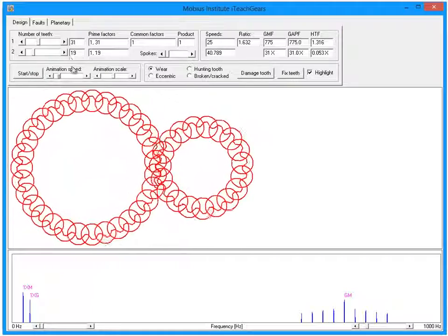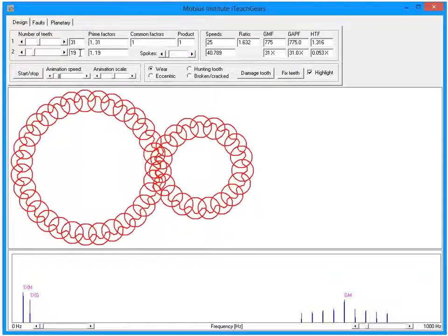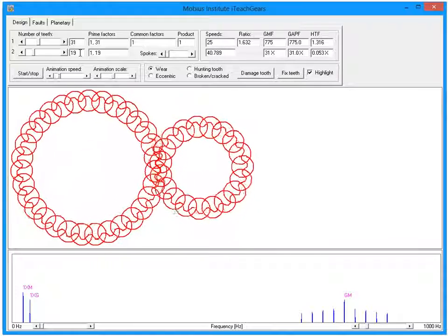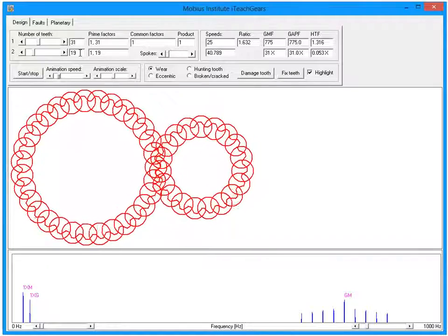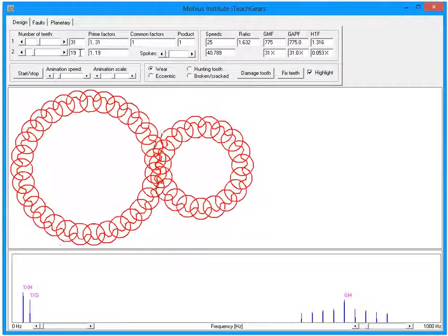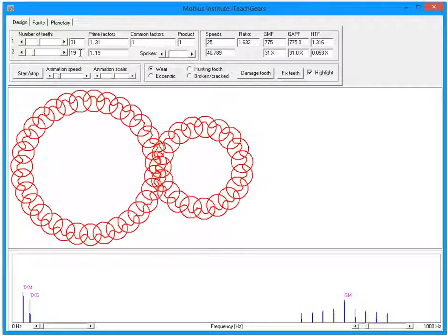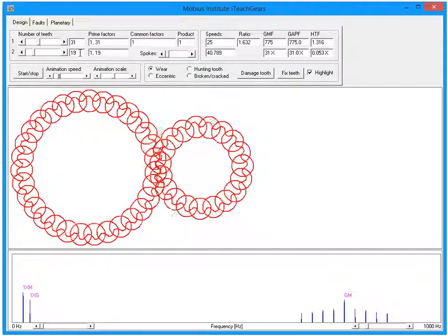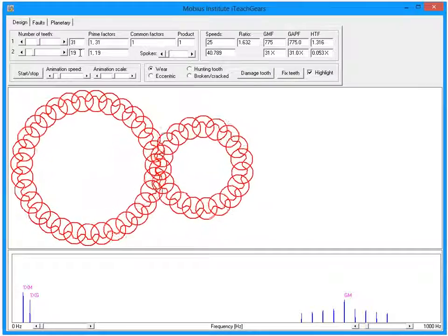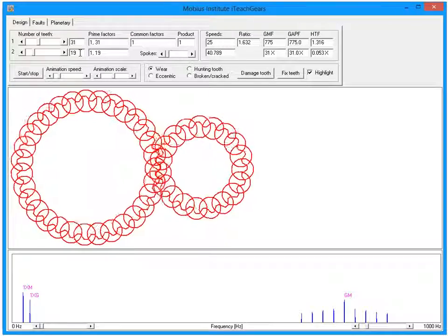And it's the same with 19. 19 is divisible by 19 and 1, but by no other number. So that makes them prime numbers. And gearboxes ideally will be designed with a prime number of teeth. And this is the reason: the wear spreads more slowly. The wear is spread evenly across all of the teeth. And therefore, as this wear spreads very slowly, as a normal process, the fact that all of the teeth are sharing in that process means the gearbox has a longer life.